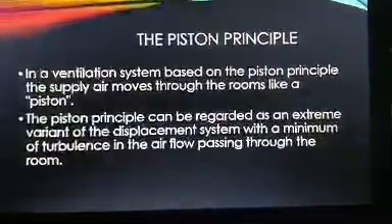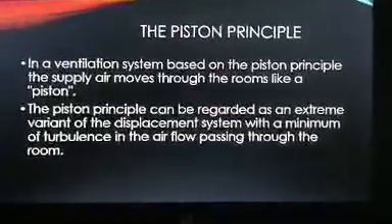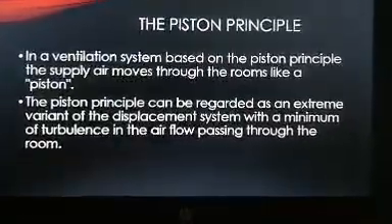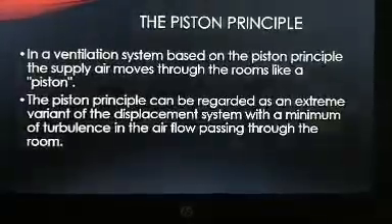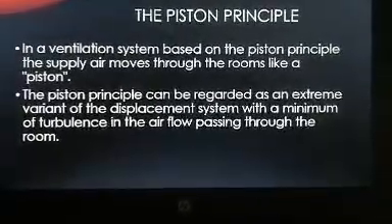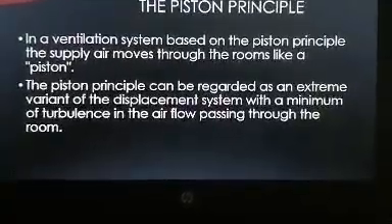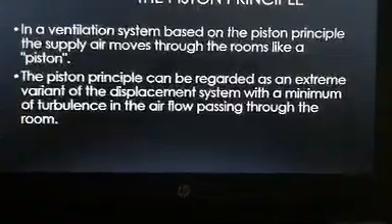The piston principle. In a ventilation system based on the piston principle, the supply air moves through the room like a piston. The piston principle can be regarded as an extreme variant of the displacement system with a minimum of turbulence in the airflow passing through the room.